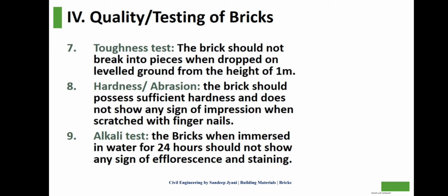Toughness test. The brick should not break into pieces when dropped on level ground from a height of 1 meter. Hardness and abrasion test. The brick should possess sufficient hardness and not show any sign of impression when scratched with a fingernail. Alkali test. The brick, when immersed in water for 24 hours, should not show any sign of efflorescence and staining.